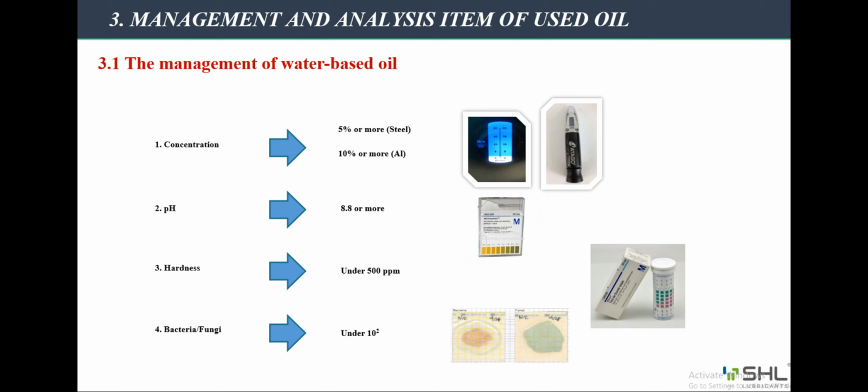Third, hard water. Untreated water always contains impurities and microorganisms. Even rainwater is not pure enough. Impurities can interact with the cutting oil, causing the cutting oil to degrade. Therefore, water treatment is essential for a high-quality cutting oil. Water quality varies according to the source of water supplied.